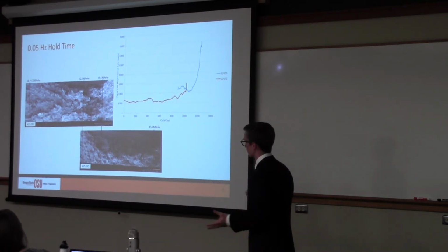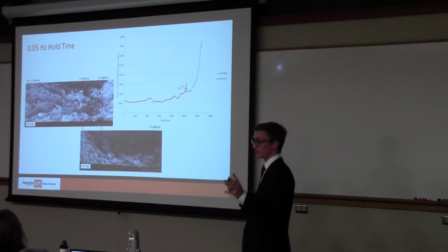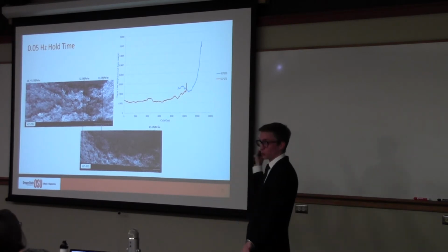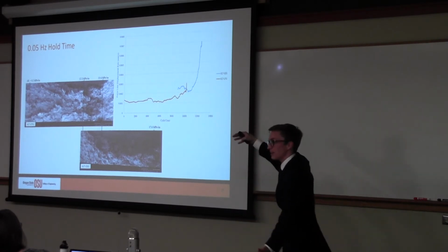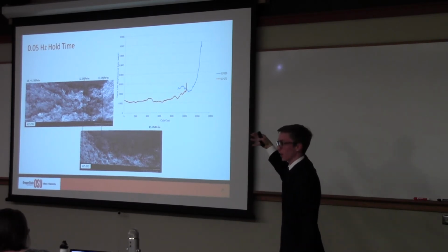And so what does that tell us? It's time dependence. And what does that mean? It means that K might not work in that regime. There might be so much creep, such a big creep zone that the elastic K field really cannot describe what's going on.